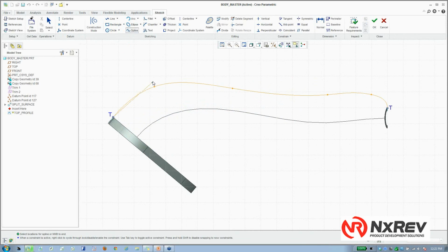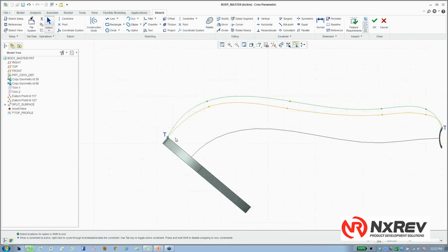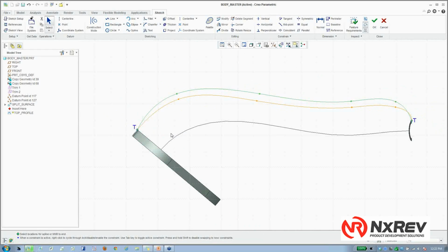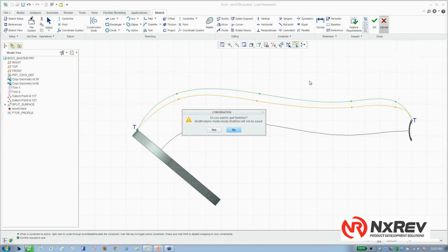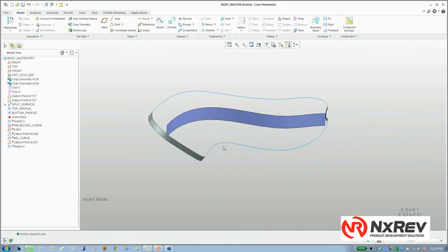I'm just kind of eyeballing it, moving these points around, and then I would make the ends of the spline tangent to the geometry that I copied in from the mechanical portions of it, the head in this particular case, so that the transition into that part is going to be nice and smooth there. Or I can decide to do it as curvature continuous.